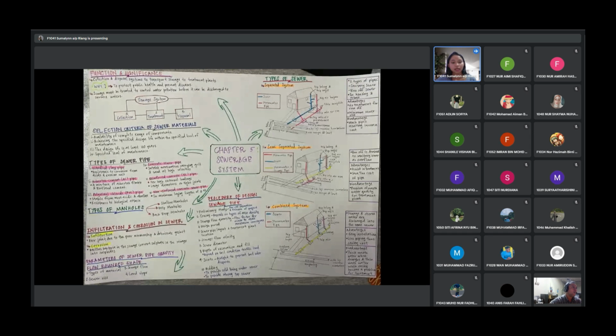In this chapter, there is also explanation about infiltration and corrosion in sewer and parameters of sewer pipe gravity flow rounded shape. And there are 10 steps under the procedure of designing sewage pipe, which are preliminary study, zoning, sewage flow quantity, design period, sewer pipe layout and treatment plant location, sewage flow velocity, sewer diameter, depth of excavation and fill, joints, and the last one is bedding.